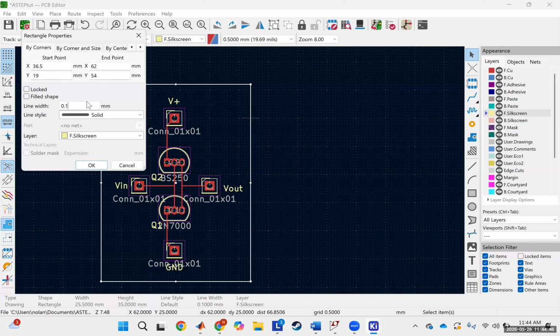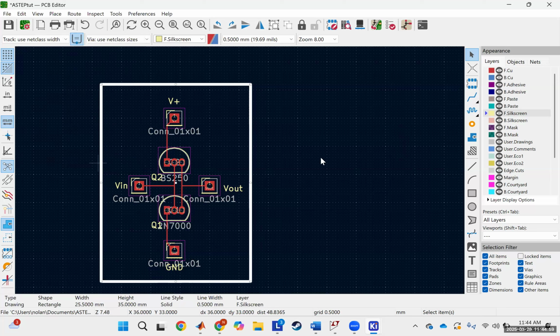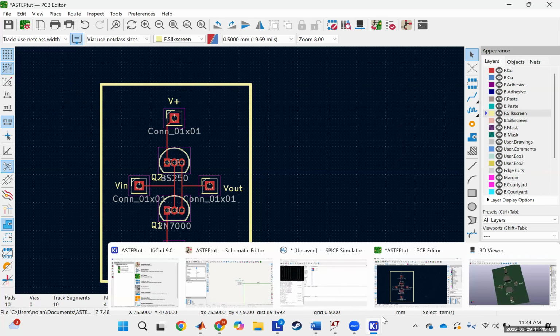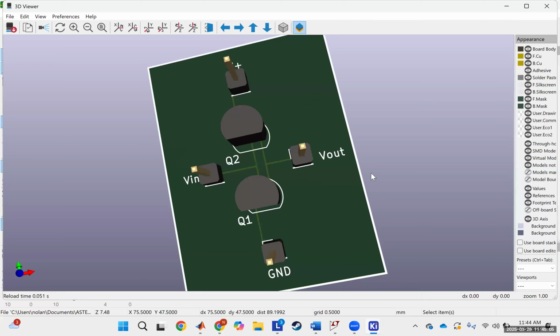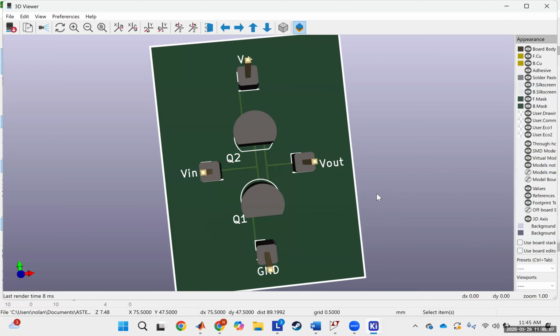And then here in this window, you'll see something that says line width. We'll want to change that to maybe, let's do 0.5 millimeter. You can see the units are set for us here in millimeters, but let's just type in 0.5 and then that'll make it a tad bit thicker. So if you go back over to your board, you'll see now we have a little white line around the outside.